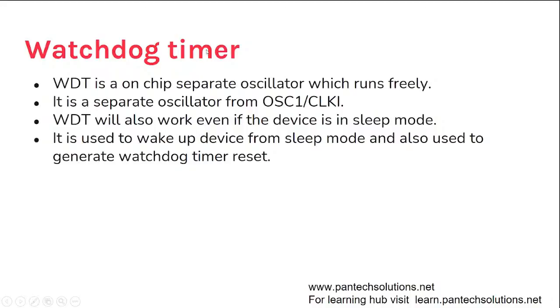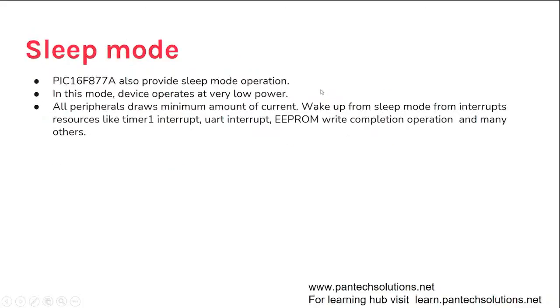Watchdog timer: it has an on-chip separate oscillator which runs freely. So the watchdog timer will work even when the device is in sleep mode, and it is used to wake up the device from sleep mode, as well as to reset it if any malfunction occurs.